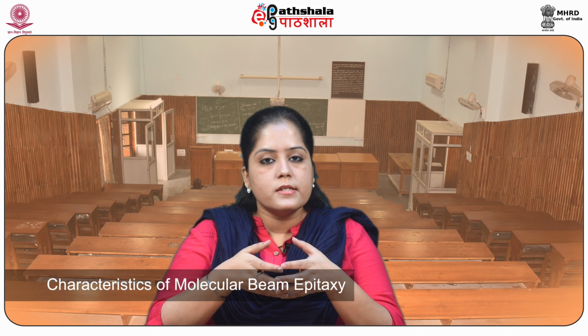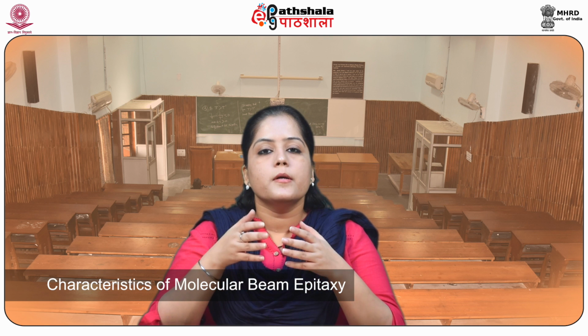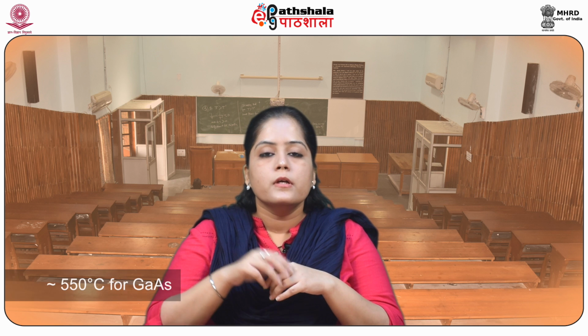So let us now discuss the characteristics of molecular beam epitaxy. Firstly, it has a low growth rate, that is around 1 monolayer, that is one lattice plane per second. It has a lower growth temperature, that is around 550 degrees Celsius for gallium arsenide.